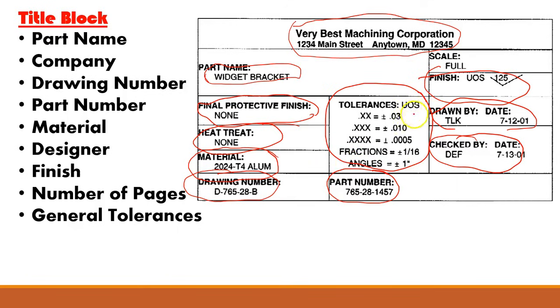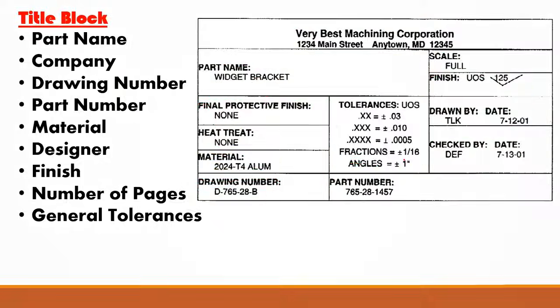So as you can see, in most drawings, they'll have a tolerance and specifications on the actual component, but if you have a drawing, a more universal tolerance that you want just carried on throughout, you can cover that in your title block. So here you've got the tolerances with the precisions, which helps you dictate what kind of manufacturing process and any type of angles, and other types of tolerances that might be universal to the part. So this is a very crucial portion of a drawing.